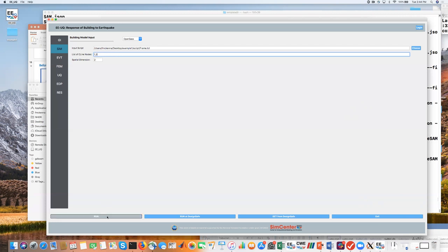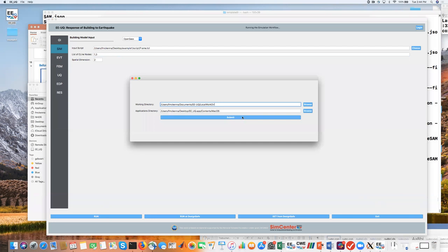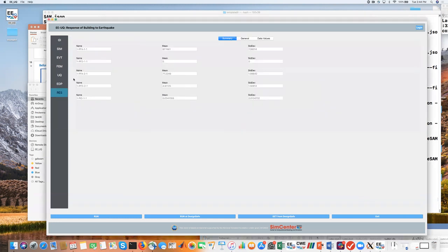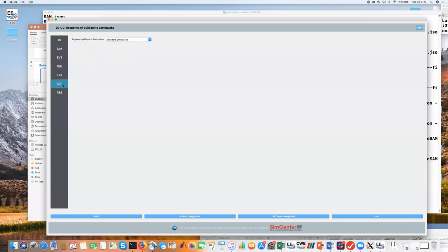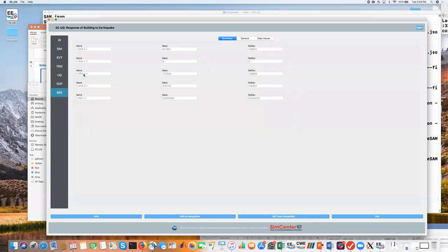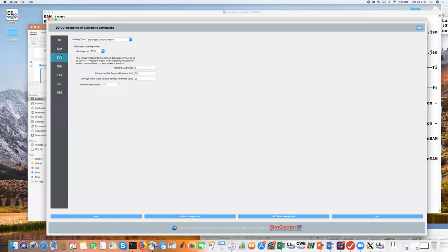Because when I now run this with the standard EDP, I see it's getting the floor accelerations at floor 1 and at floor 2. And the interstory drift. So it has to know, I have to know what those nodes are to actually get the displacement at particular floor levels. So those column line, you're specifying the nodes at a column line for which these response quantities, the floor accelerations and the interstory drifts are actually calculated from, if that makes sense. I think it makes sense.